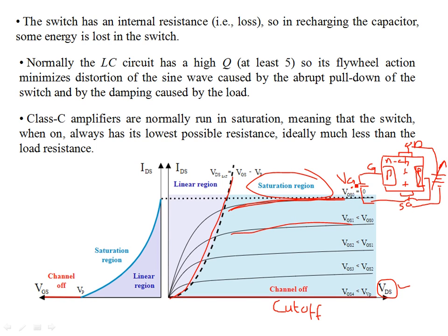Okay, so as VGS, which is of course less than 0, is increased in the negative direction, this is reverse biased. It's negative. The depletion width is going to increase. As the depletion width increases, you see the channel width reduces. The channel width reduces, and the flow of electrons from drain to source reduces.